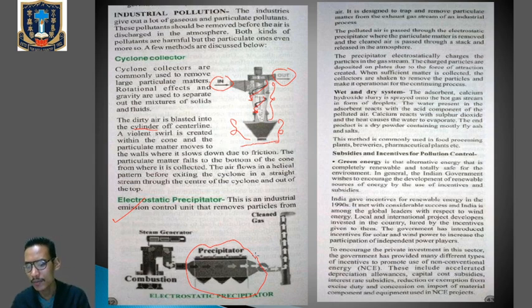So those dust particles which are present in the air that passes through the electrostatic precipitators will be electrically charged. Clear? And those charged dust particles will be collected or will be attracted towards the plates. Plates will be applied over there, and those plates will collect the charged dust particles, and the air will be free from those dirt particles.